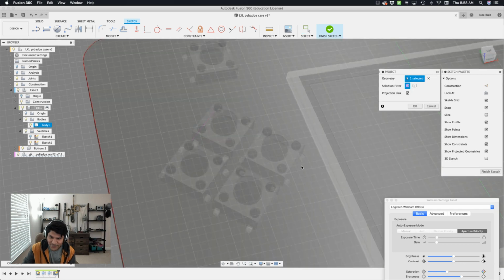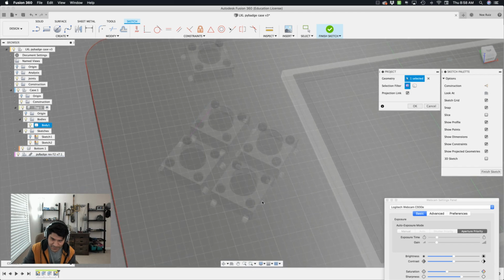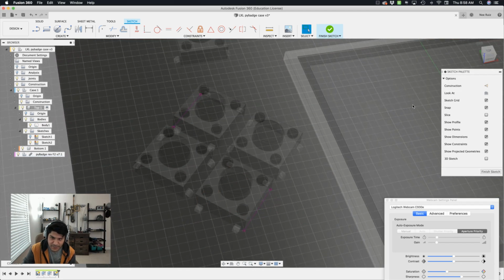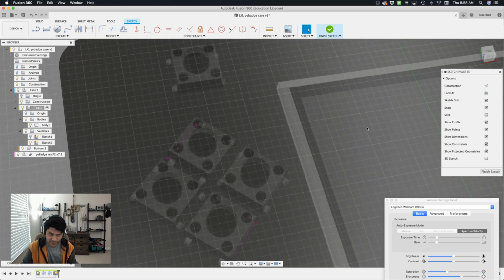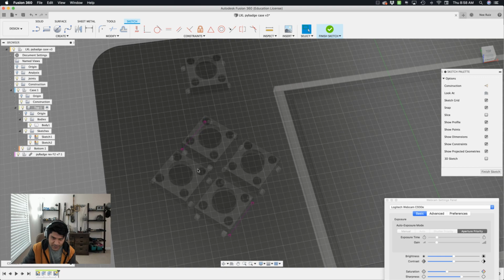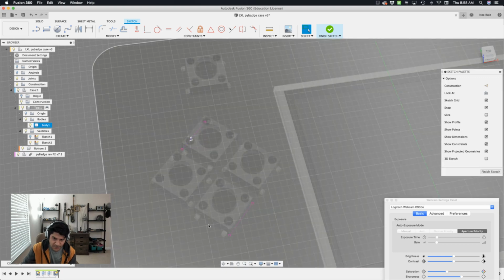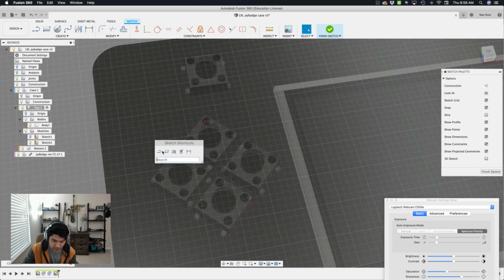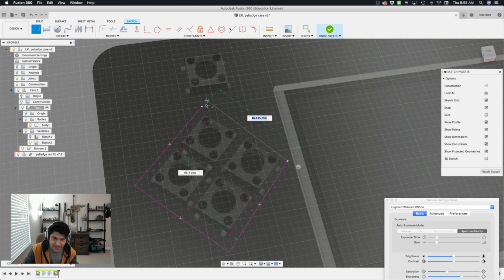Okay, so I got that first one, and then I'll have the opposite on the back here. I'll have this edge right there, and then I'll hit OK. That's really all I need for creating this kind of cutout. Instead of using the edges from these 2 buttons, I can just use the dots here. So I'll grab my line tool, and I'll start drawing this kind of diamond shape. It doesn't have to be accurate yet because we're going to fully define it once we create our lines.